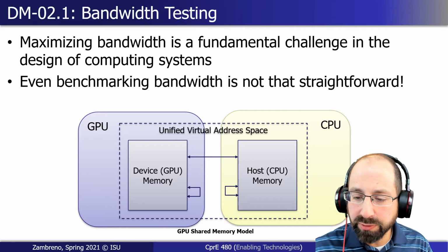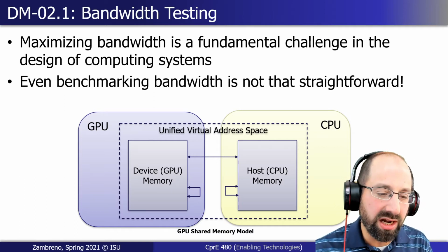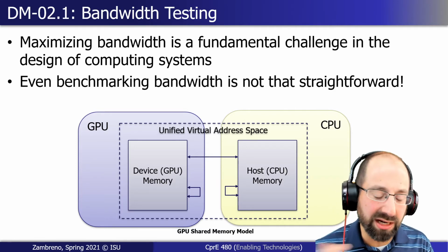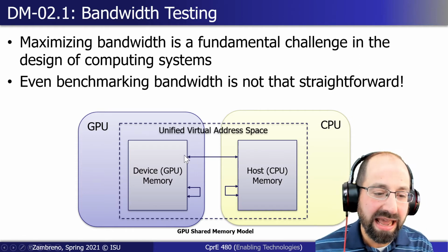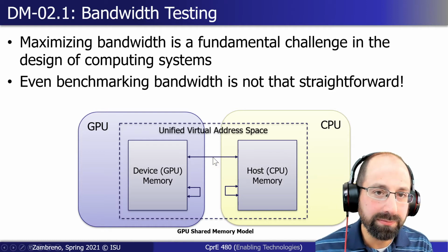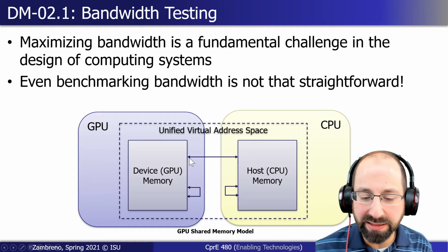Yep, possibly. So when we do those DMA actions, usually at least there's some sort of internal storage of the DMA engine itself, at the very least to buffer enough so that it can do large block transfers at a given time. But you can, in fact, just request a single byte, and you're going to pay all the penalty of having that single byte of copy and get really none of the benefit of the potential throughput of such a high performance system there.